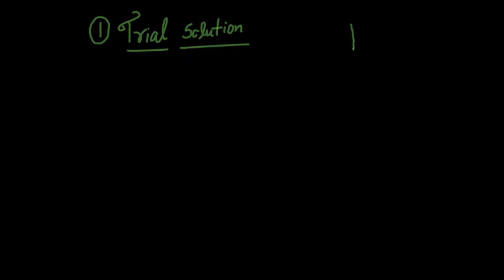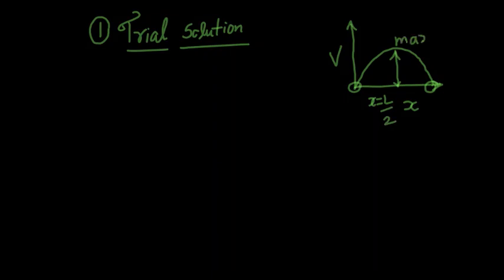Well, if you plot the value of deflection of the beam along the y-axis, and you plot the value of x, which is an arbitrary distance from the left extreme end, you are going to get a deflection curve something like this. The deflection at the left extreme end is 0, and the deflection at the right extreme end is 0. Since this beam is subjected to uniformly distributed load, the loading is perfectly symmetrical. The deflection at the center, at x equal to L by 2, is going to be maximum. So the deflection spikes at the center.